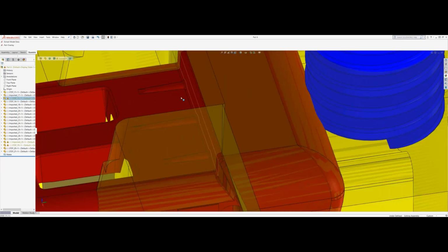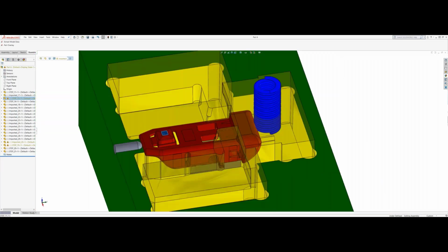And this is where it mates to. You can just imagine a rectangular tube that this slides into, and this is exposed. And then this is the little snap feature that once it's in, this would snap and pop back up. So we had some core outs here, some other mating areas. We gated on this end to hide the gate, so we wouldn't have any gate vestiges on the outside of the part.